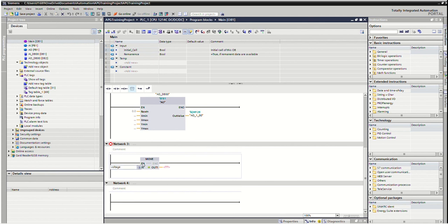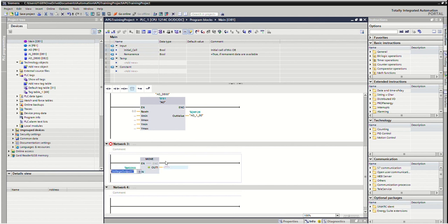The voltage output 1 at MD200 moves to the analog output block to raw in. That raw min, x min, x max, y min, y max is set by default in the function block. Otherwise, you can set some other value in the DB.